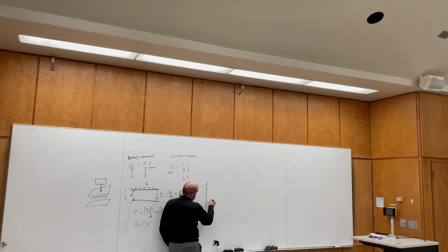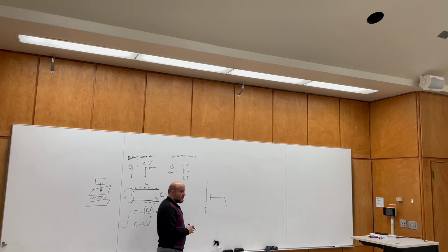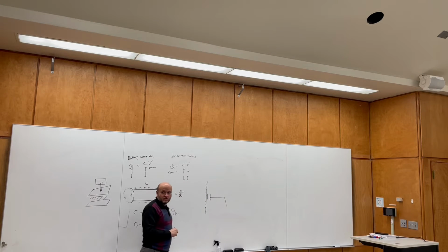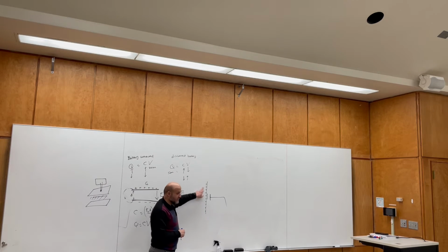And then they place this in front of another plate, which is connected to a circuit of voltage. So this is a capacitor. Now when you speak in front of this microphone, the membrane is going to move closer, and that changes the capacitance because D changes, keeping the Q constant. This is isolated. It's not touching anything. Then that's going to change the voltage between these two points.